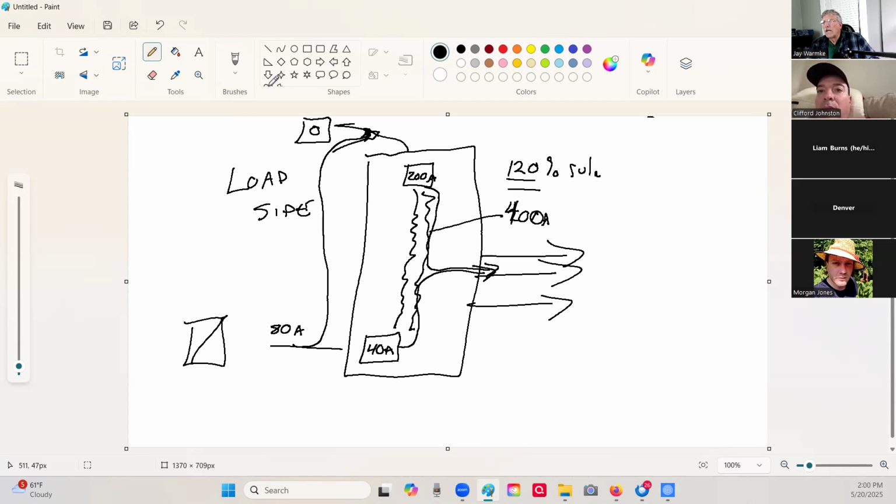So it adds cost. If you're doing it this way, well, shoot, all you need to do is just turn off the main. Now your box is dead. Wire up a 40 amp breaker, slap it in there. Once the connection's all made, turn the main back on, and you're all set to go. So it didn't require an electrician. It's a cheap and easy connection.